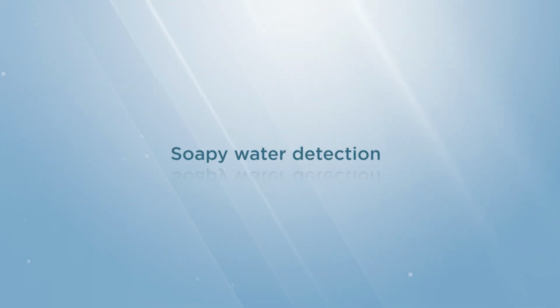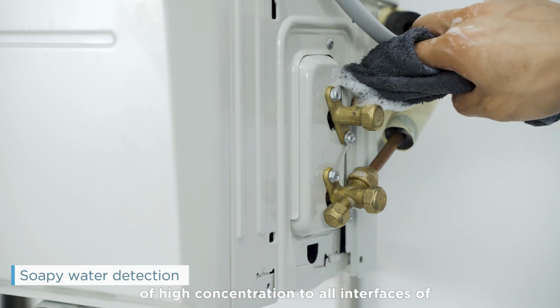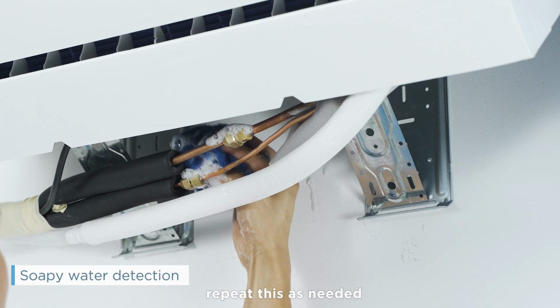Soapy water detection. Apply soapy water. Washing powder of high concentration is applied to all interfaces of nuts with a brush, then observe for 2 to 3 minutes. Repeat this as needed.